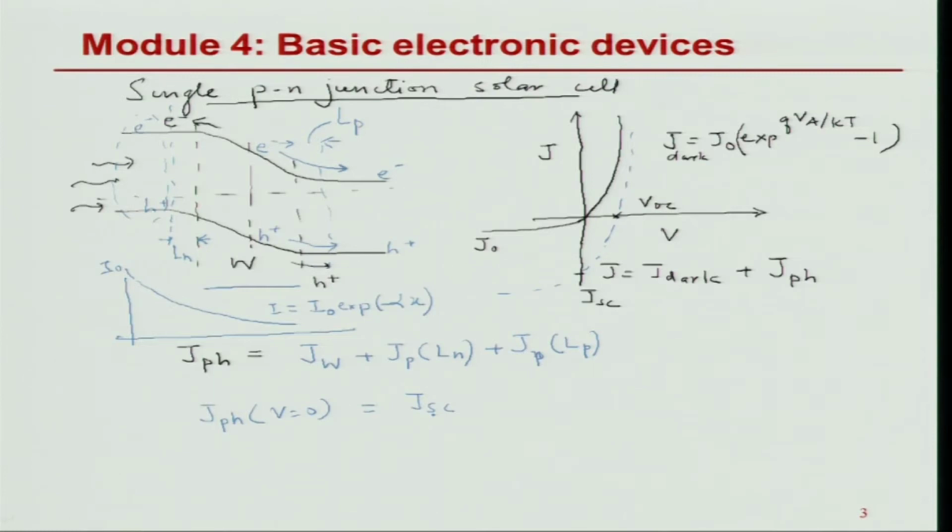So this gives me the picture inside the depletion region, and as we go further, what would I need? In order to collect as many electron holes as I can, I need to have a large W. I should make my device such that there is a large built-in region, and I should have less dead n and p region.